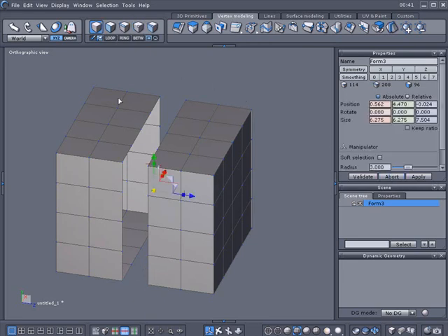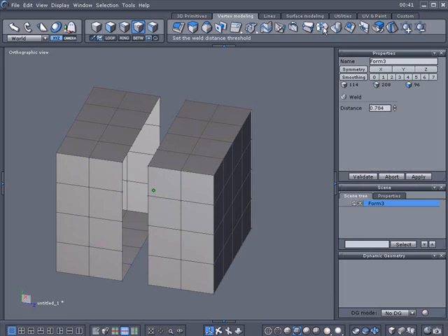Now, let's say I want to weld this whole thing together, put this cube back together. This time, instead of selecting a point, I'm just going to select the average weld. And this little gap here, it's going to try matching up all these points. If they're pretty close to across from each other, it's going to try finding it by the distance.